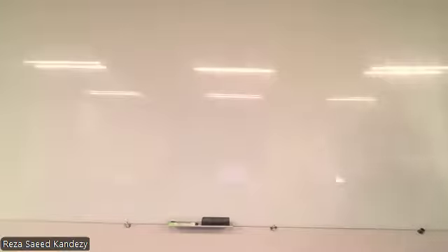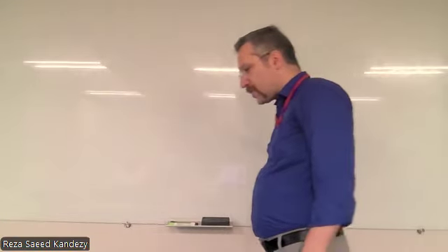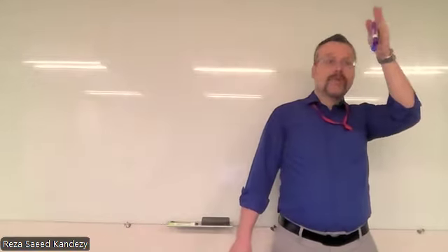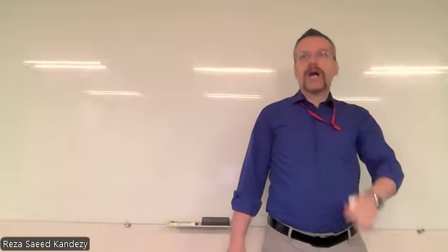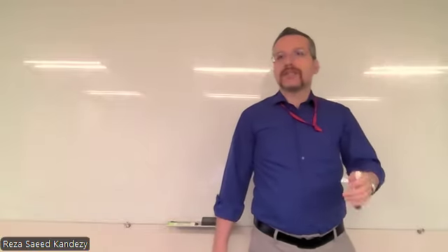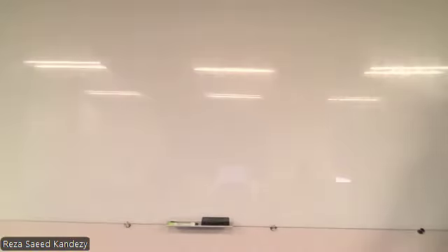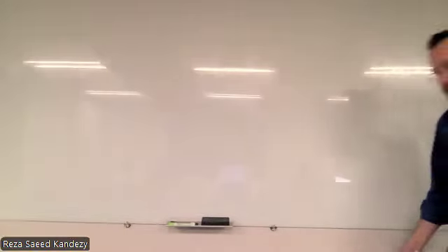And we already also talked about marginal stability, which was when we only have poles on the y-axis or imaginary axis. We found out that that actually means a sustained oscillation.